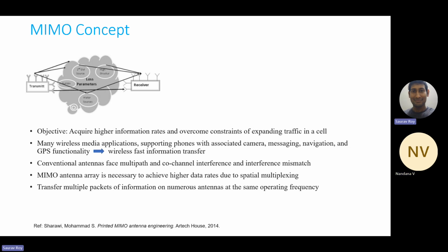Understood the scenario, right? Yeah, tell me what you're saying. In diversity, 4 antennas will transmit the same data, and the receiver will receive the same data 4 times. Now we can form this data as a matrix, right? From 4 different antennas we can form 4 different rows of a matrix.